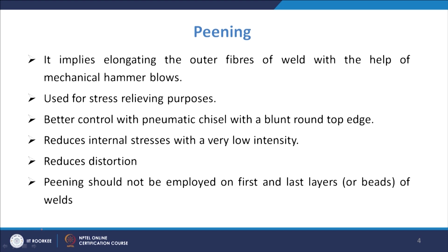When it is properly applied, it will cause plastic flow. When we apply the layers and do the peening, it causes plastic flow in the welded zone, and it subsequently relieves the restraint which is producing the residual stresses. That is how it decreases the stresses.